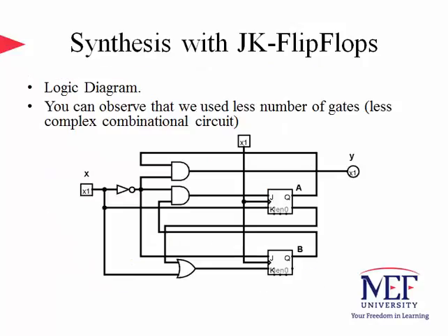After finding out the J and K inputs of flip-flops in terms of state variables and inputs, like X, the output Y does not change in the JK implementation, and it's still AX', by the way. So using the flip-flop input state equations as well as the state equation for Y, we finally obtain the logic diagram, and that's how we draw it.